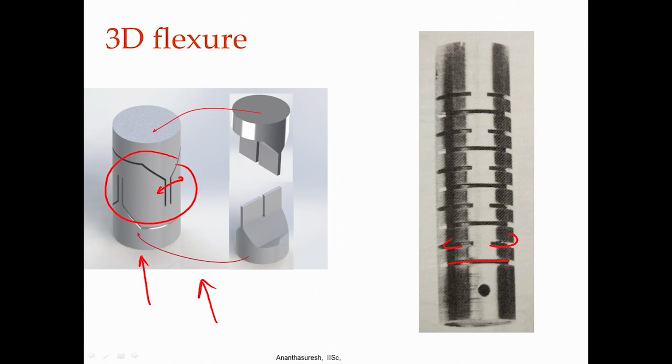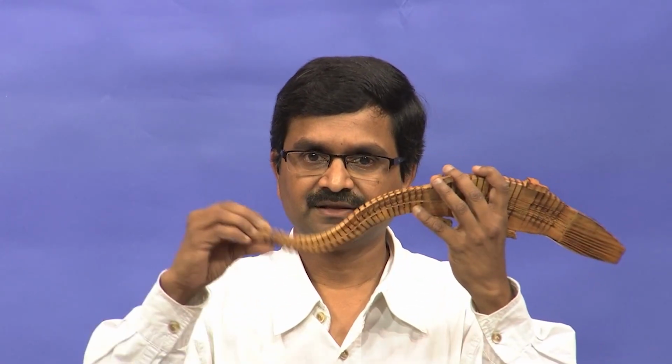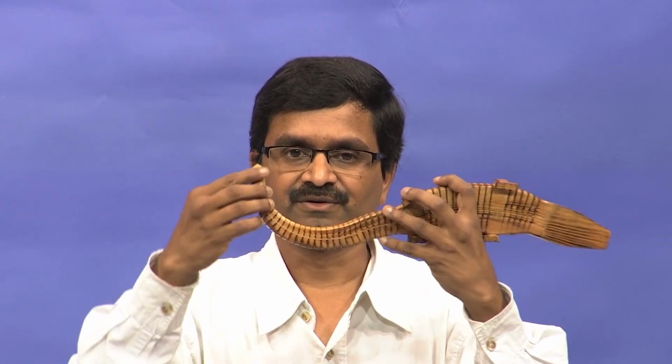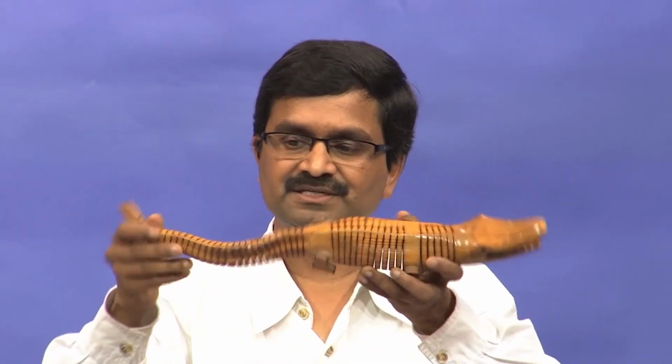And you might also have seen these toys. So, what you can do with elastic flexures. So, here is a little toy with wood, where this tail, like what I meant, that if you take a cylindrical rod and put this thing, you can do that. It has actually that. So, this crocodile toy that you find in the markets, it is all with flexures. So, with flexures you can get any amount of displacement, but at each elastic pair the motion is limited.